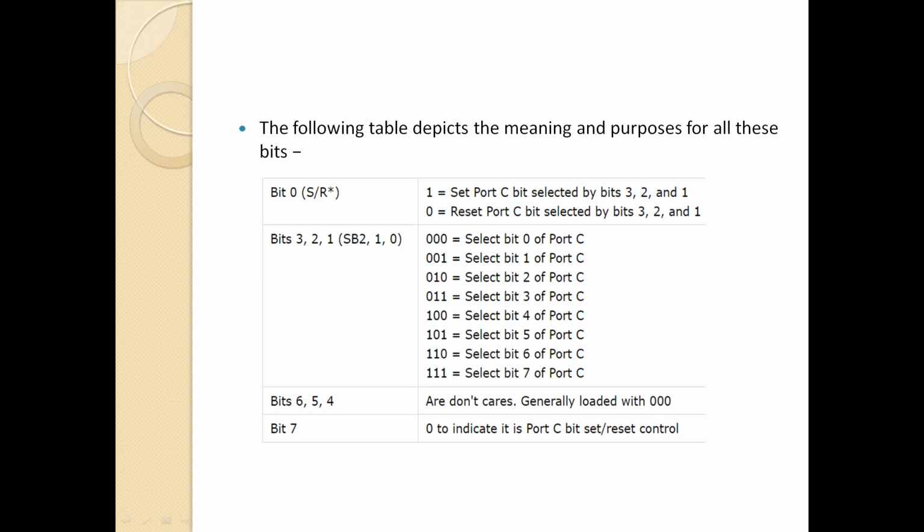Bits 6, 5, 4 are don't care pins, so generally they are loaded with a 0, 0, 0 signal. Bit 7 is 0. This indicates that the 8255 chip is operating in the BSR mode. And the port C bit is set or reset.